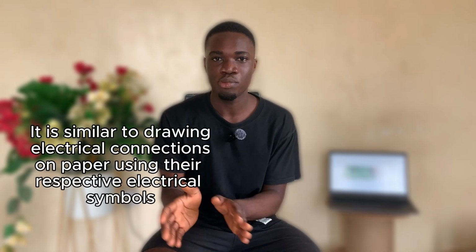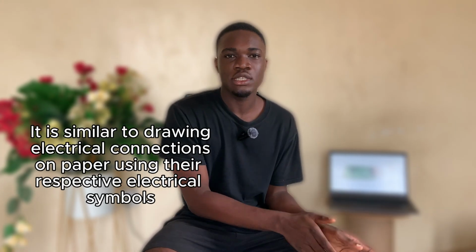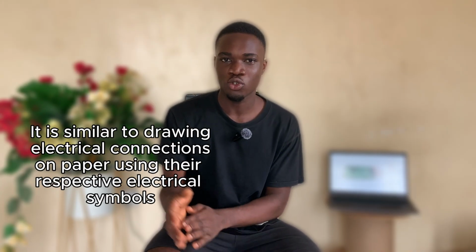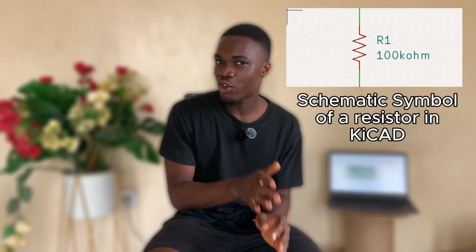The schematic basically is a blueprint of how the connections should be. Whatever PCB you are making has a schematic of how the connections of the PCB should be, using electrical symbols to create the connections for the PCB. Once you are done with the schematic, you then convert your schematic into PCB.